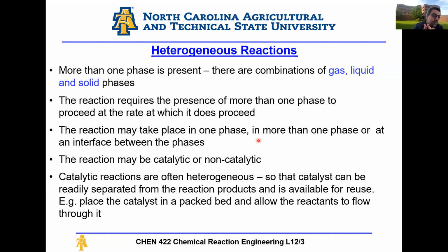Okay, and in a heterogeneous reaction, the reaction may take place in one phase, more than one phase, or even at the interface between the phases. I'm not sure if you've touched on this in mass transfer. However, if I have 2 phases in contact with each other, you probably touched on this when talking about Henry's law, for example. I have, for example, gas and liquid. I have an interface between them. I have my gas bulk, my gas-liquid interface, my gas film, my liquid film, and then my liquid bulk, right? And each of these stages has its own resistance to flow, depending on the nature of the species and the operating conditions.